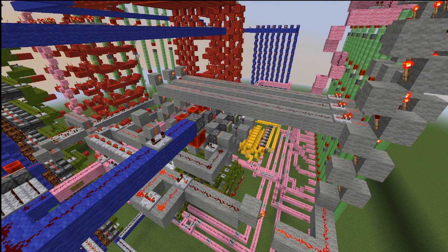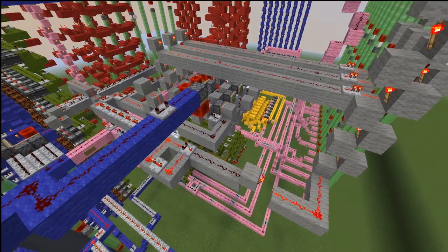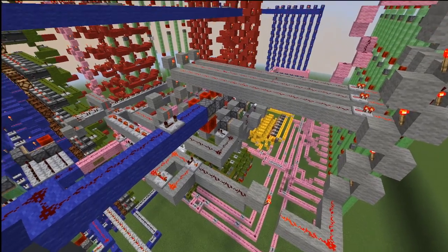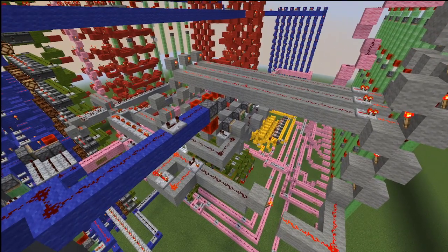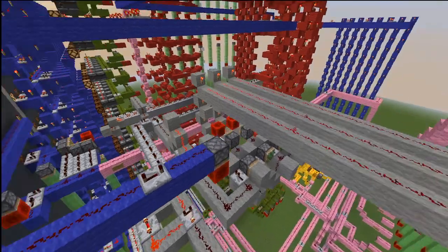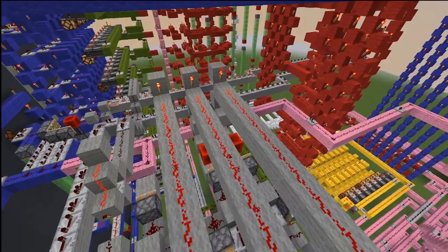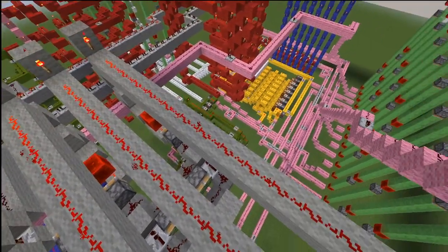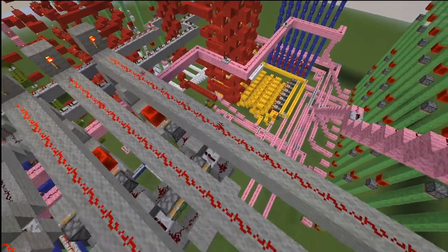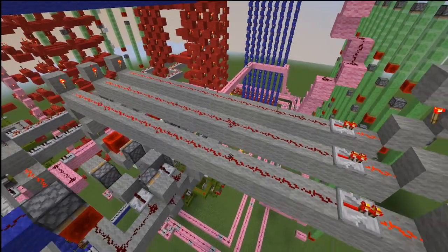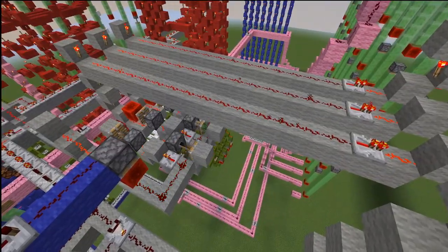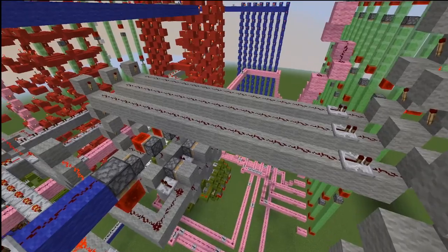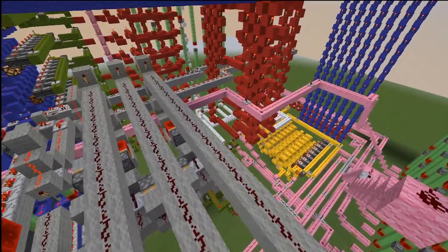And the reason it took so long to update the program counter down there was because I had accidentally forgotten that when you get binary 0, 0, 1 here, that doesn't do anything for jump. Normally that would increment the program counter for any other macro instruction, but for jump, it doesn't do anything.